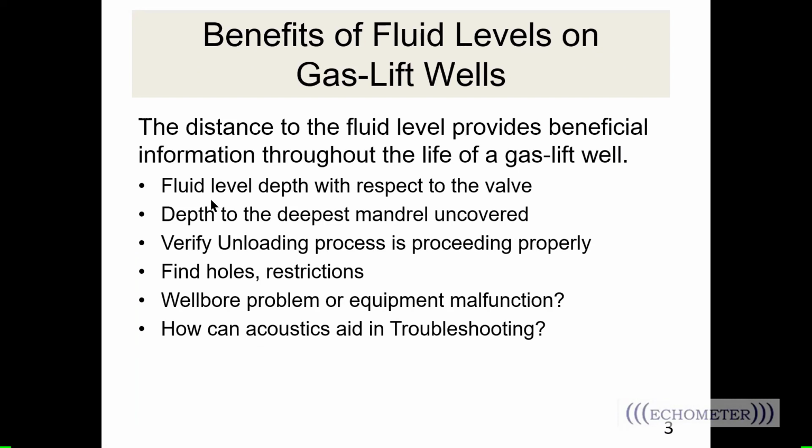All right, so the distance to the fluid level provides beneficial information throughout the life of a gas lift well, from the initial unloading of the well to maintaining production, and even into troubleshooting the well. Using the acoustics, the fluid level shots can play a crucial role in understanding the well's performance. So we can see the fluid level depth with respect to the valve.